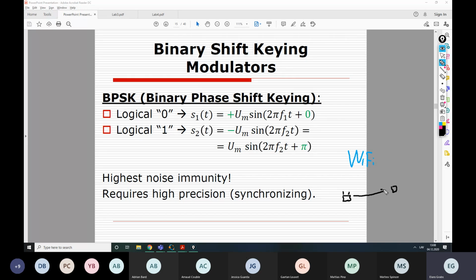The further you are away from that router, the slower data is sent, but the safer at the same time. So basically we need to increase noise immunity, and as a last resort for the limiting distance, let's just say so, we are using binary phase shift keying. And after you move away even further from your router, there is nothing that can help you to receive that signal better. So you need to get back into the coverage area of this router to get a stronger signal and higher data rate.